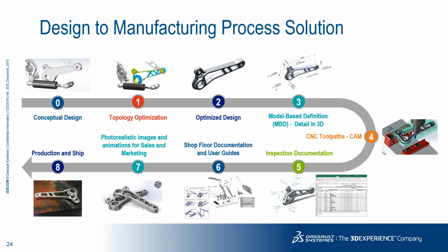Once I have this optimized design, I may want to do my detailing on it, and I can either do 2D drawings, or even better, I can do 3D dimensioning and tolerancing. We call that model-based definition, all right? You can put all your dimensions and tolerances in the 3D model, and the beautiful thing about that is when you go to do your CAM programming with SolidWorks CAM, you can actually see all those dimensions and tolerances, and we can actually use those. We understand those dimensions and tolerances.